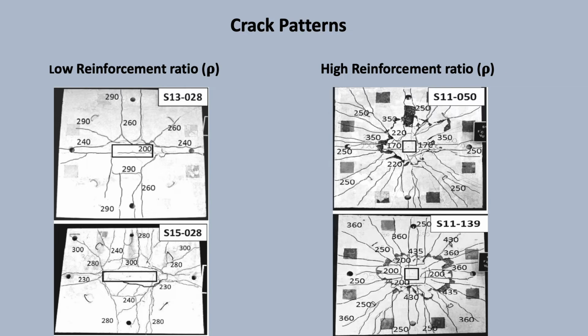On this slide are shown the crack patterns associated with a low reinforcement ratio and a flexural failure, and the crack patterns associated with a high reinforcement ratio and a punching shear failure.